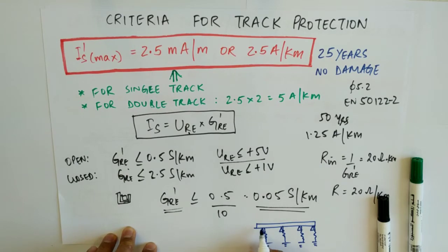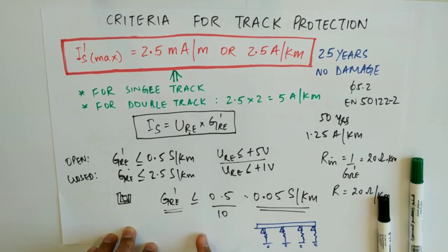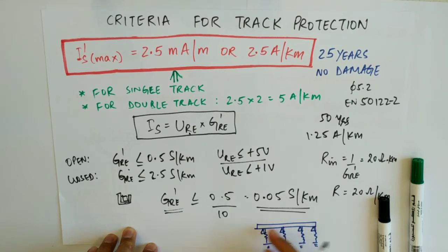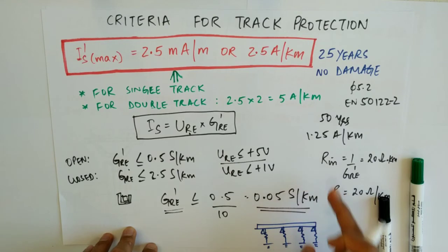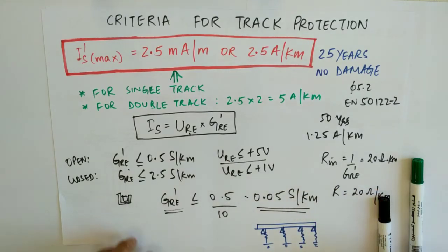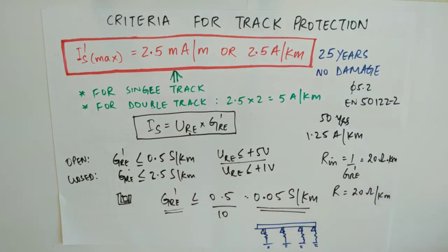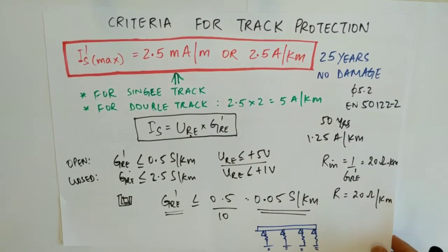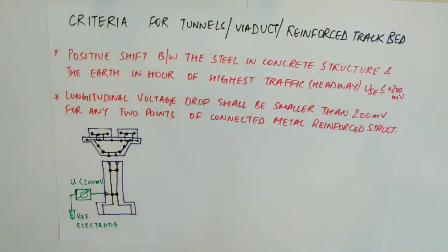So if you go for suppose 1 kilometer, there will be a lot of resistances in parallel. So once they are in parallel, then the effective value will decrease, not increase. So that is why the insulation resistance decreases with kilometer. Also, I will give a derivation at the end of this lecture, for those who want to enjoy the feel of why insulation resistance decreases with length.